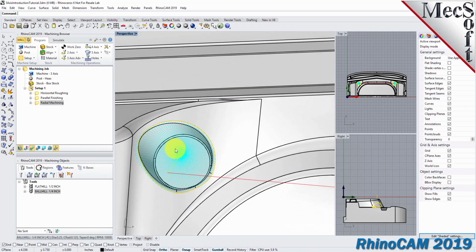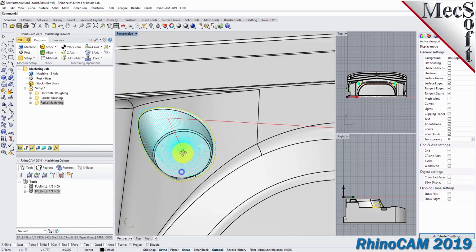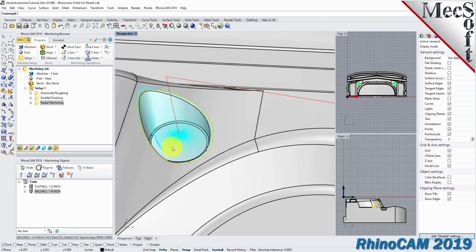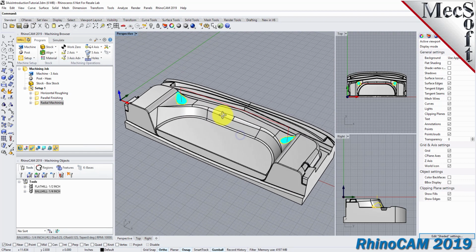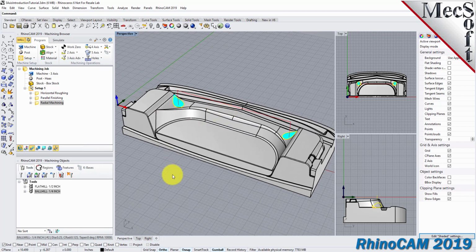This creates a finishing toolpath for these 2 features. As you can see, the linear cuts radiate out from the center of the pocket, and the tip of the tool stops at the perimeter that we selected. Now, with the toolpaths complete, we're ready to post-process to an output text file containing G-codes that can then be sent to the machine tool to actually machine the part.